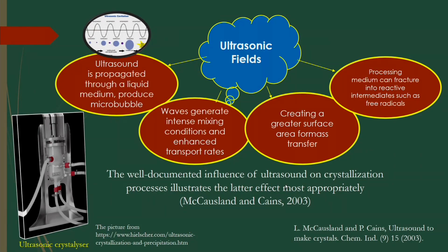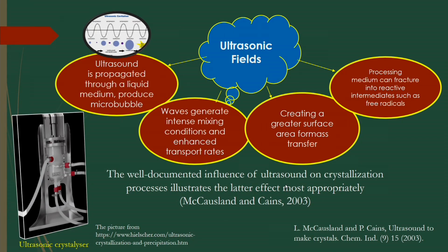Two immiscible liquids are there. You have to produce droplets of that organic solvent like paraffin or decanol. If you use decanol to extract propionic acid from the water, you have to produce droplets of the decanol or paraffin, through which the mass transfer will happen. So, in this way you can use ultrasonic waves to create finer droplets to extract propionic acid from the water. That is why intensification based on ultrasonic fields is used for this particular extraction operation.